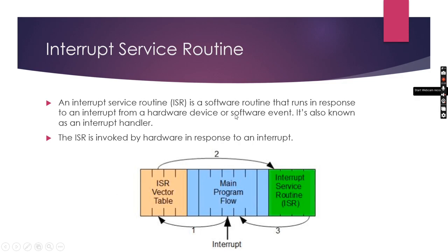It is a software routine that runs in response to an interrupt from a hardware device or software events. It is also known as an interrupt handler. The ISR is invoked by hardware in response to an interrupt. When an interrupt is applied to the main program, it forms a loop-like structure with the interrupt service routine and the ISR vector table.